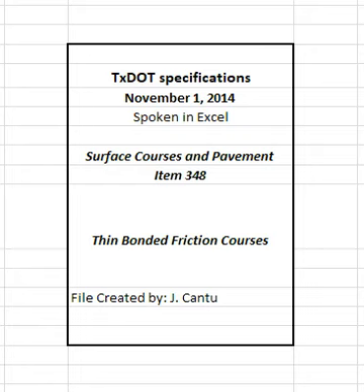5.2 Asphalt. The asphalt weight in tons will be determined from the total weight of mixture. Measured asphalt percentage will be obtained using Tex 236-F or asphalt mass flow meter readings for PG 76 mixtures, as determined by the engineer. Measured asphalt percentage will be obtained using asphalt mass flow meter readings for AR mixtures. Provide the engineer with a daily summary of the asphalt mass flow meter readings for AR mixtures unless otherwise directed. Add the recycled binder content to the flow meter readings when calculating asphalt quantities.